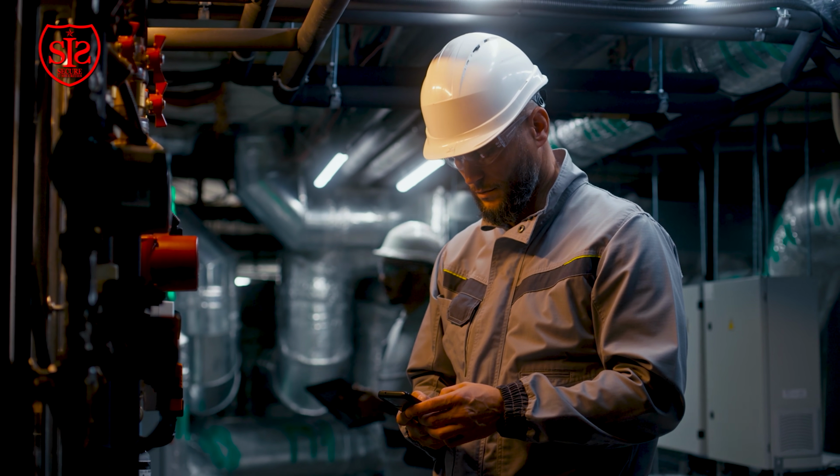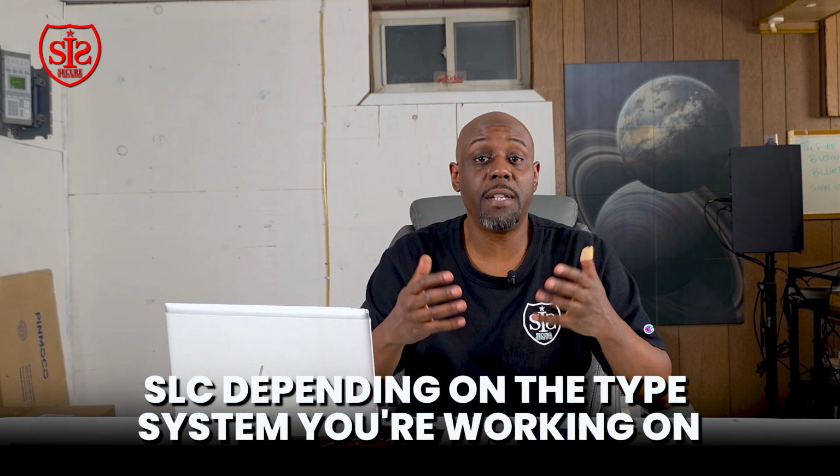Now I want to talk about principle number 3, and this is the costly mistake that I see most technicians make out there in the field. There are always different load requirements and device requirements for each particular loop. It is your job to know on that SLC, depending on the type of system you're working on, how much current these devices are going to be drawing, whether it be on an SLC or on a NAC loop, because I know on certain systems, if you overload a NAC circuit, it's not going to be able to drive the entire output and activate all of the horn strobes.